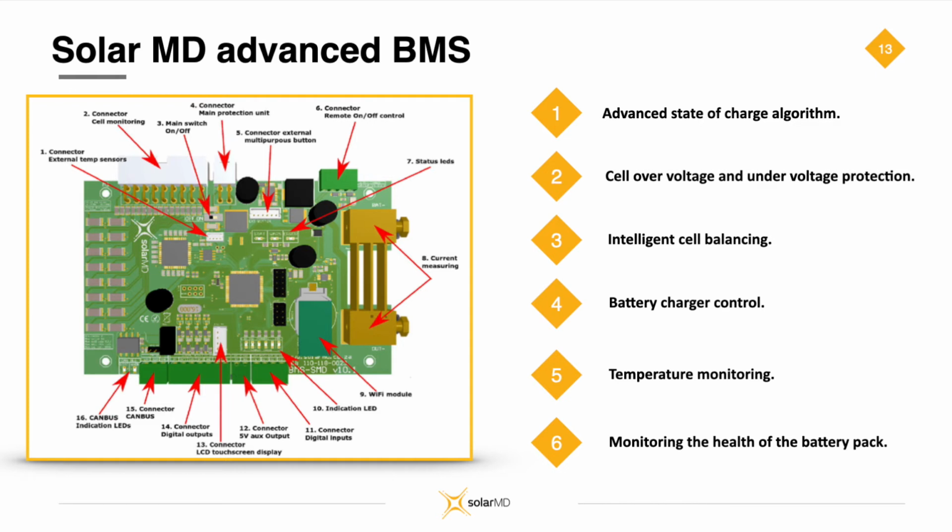The BMS has 3 status LEDs toward the top side and 6 at the bottom. If a warning or error is active, the front intelligent power button will indicate this. Yellow indicates that a warning is active, and red if an error is active. In normal status, the bottom 6 LEDs can be set to off, show current, or show capacity.